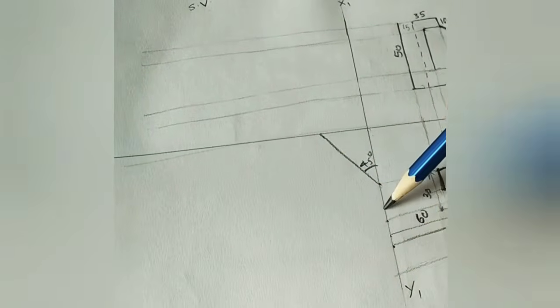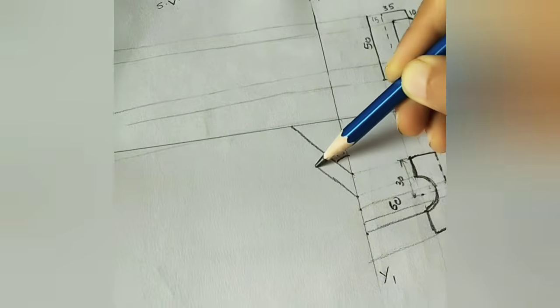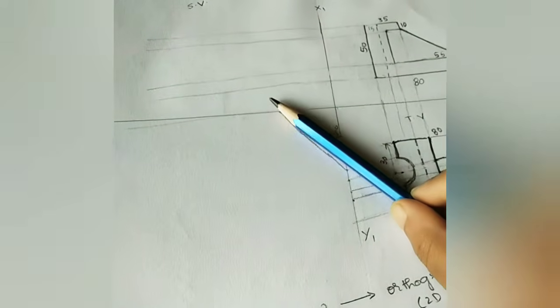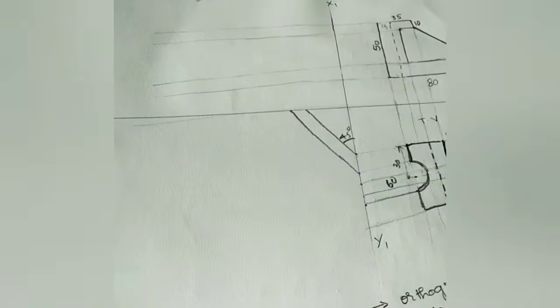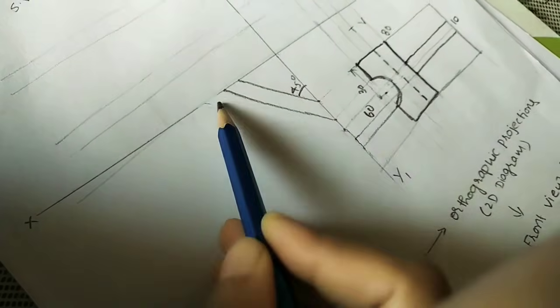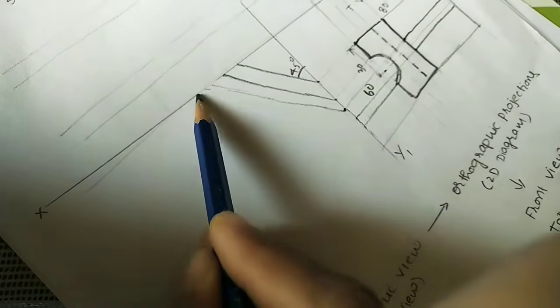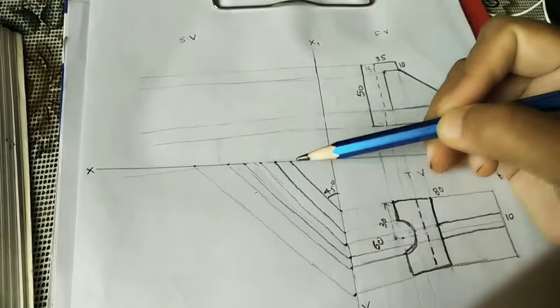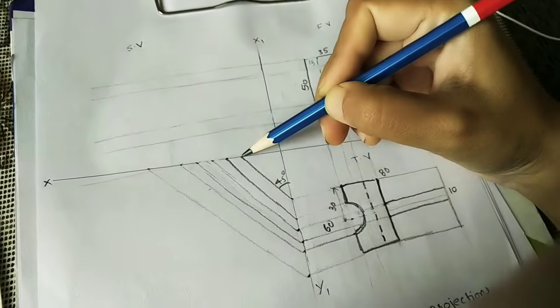Now we have shifted this point to this point here, and from all these points we can take the 45 degrees lines, or we can take parallel lines. Okay, by fixing the drafter scale here, we can move the scale at all the points for getting the parallel lines. For getting this line, here we have to do the parallel line. So at all these points, do the vertical projectile lines.